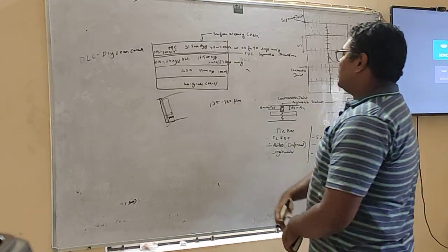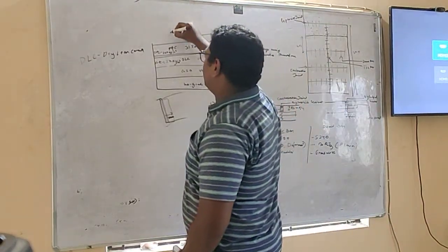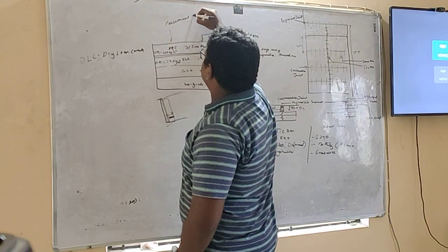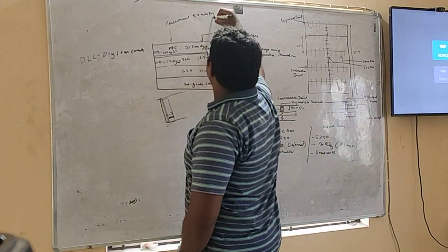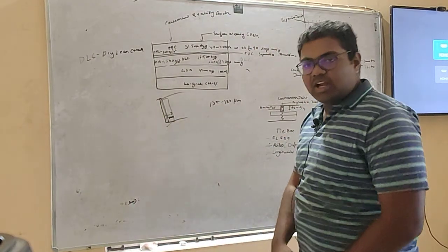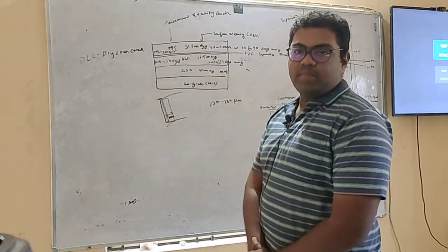And after laying our PVC or separation membrane, we will move to PQC or pavement quality concrete. It is again procured from our RMC plant and transported using transit mixers.